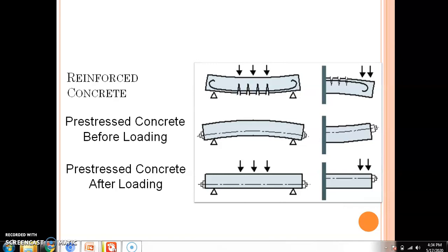In brief, I will tell how the prestressed concrete structure varies from reinforced concrete structures. Both have similar materials; both have concrete which is reinforced by some type of steel. But in a reinforced concrete structure, the reinforcement element is not stressed, whereas in a prestressed concrete structure, the reinforcing elements, strands or tendons, are stressed in such a way that they create stresses in the concrete which will nullify the stresses that will be created upon imposing loads. Thus it reduces cracks and also reduces deflection.